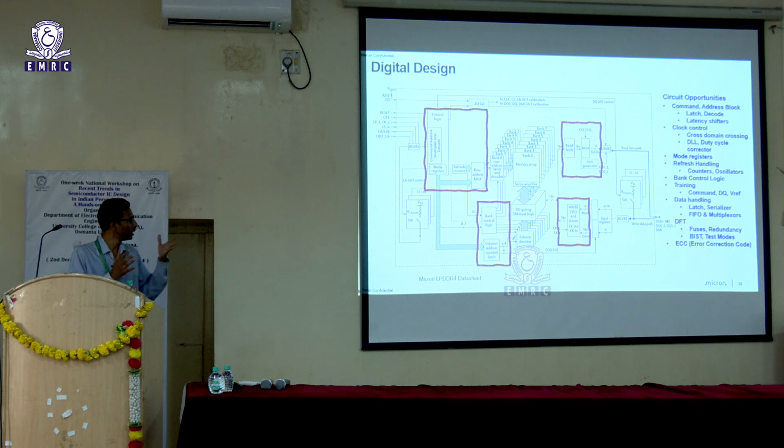So you essentially configure your DRAM in such a way that, okay, if you are doing a high speed operation, this is the kind of blocks that I'll enable, and if you're doing a low speed operation, you have a different set of things to be enabled. And mode registers come in handy to ensure that you have all those things captured in a proper manner. So you'll have your frequency set point. Let's say you're operating it at 200 megahertz.